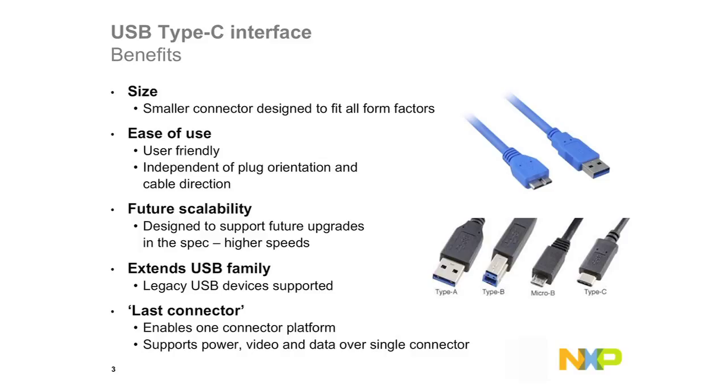It can support USB 3.1 Gen 2 speeds, which is 10 gigabit per second. Most of our designs today are USB 3.1 Gen 1, which is 5 gig. But in future, everything is going to get upgraded towards USB 3.1 Gen 2. And at the same time, it is fully backward compatible, and it supports USB 2.0 signaling as well.